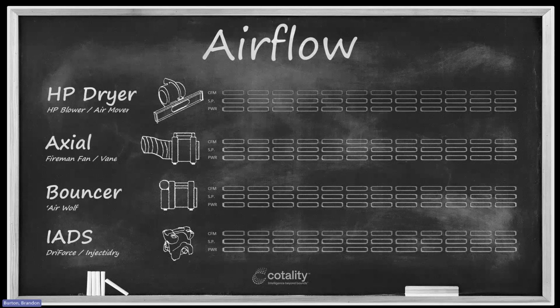a huge red flag for drying systems, because if we're dealing with anything more than a couple hundred square feet of wet area, sometimes the number one limiting factor to how I can dry that structure is my available power infrastructure. So I'm always very, very aware of how energy efficient my drying systems are, because I can shoot myself in the foot real fast if I start using high amp equipment in the drying environment. So those are my three specs: CFM, static pressure, and power efficiency.